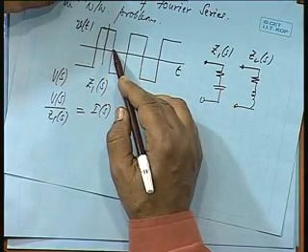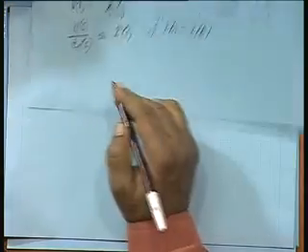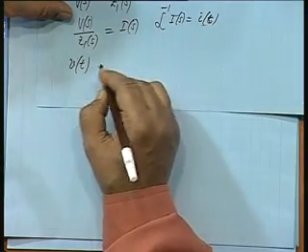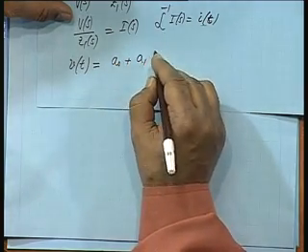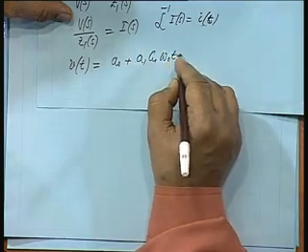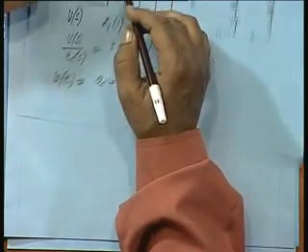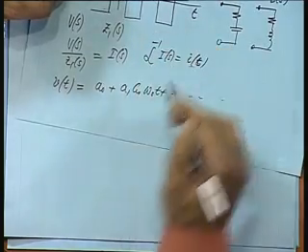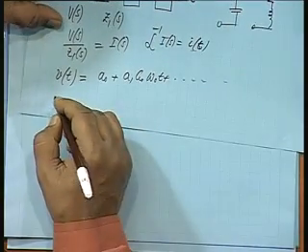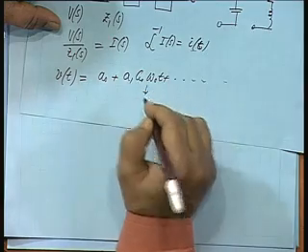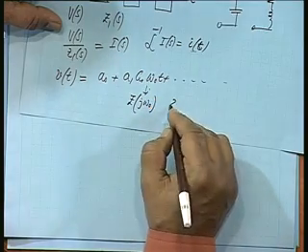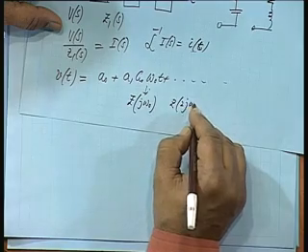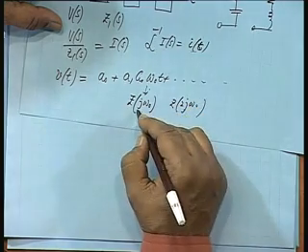What will be the expression for I(t)? Now, instead of going by this Laplace transform and then taking inverse, we may find out the Fourier series, the Fourier components for this periodic function. So, V(t) we can express in terms of A0 plus say A1 cos omega naught t and so on, and in this particular case Bn terms will be 0, otherwise Bn terms will also be present. Then for each frequency we calculate what will be the corresponding Z(j omega).